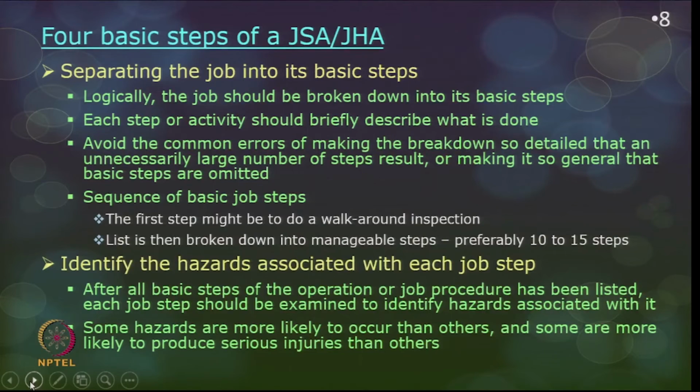The next step is separating the job into its basic steps. For example, it may be loading and unloading of steel reinforcement. This example I have covered earlier also. For this you may have at least 50 steps. The truck may have arrived at the site, then you call the engineer for weight checking, then they take the weight of the entire reinforcement, they enter it in the register, and then maybe they do a preliminary test if required, and then the truck enters the site, and again you wait for the workers to unload the reinforcement.